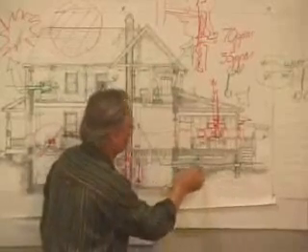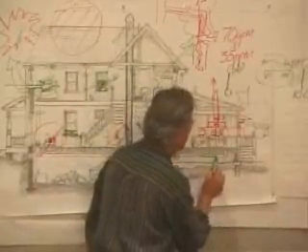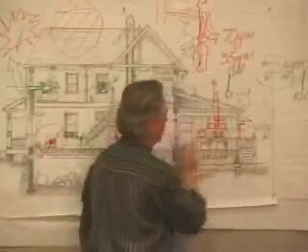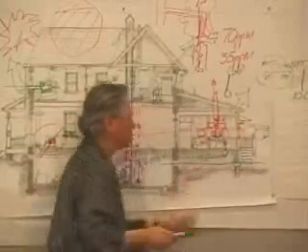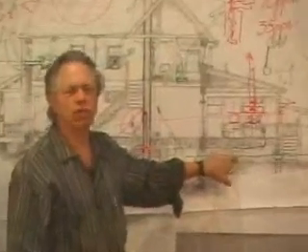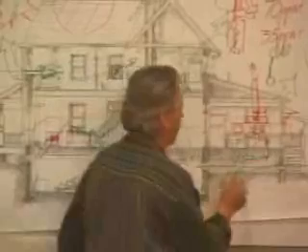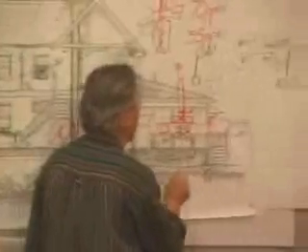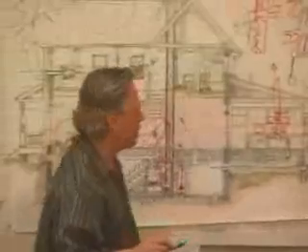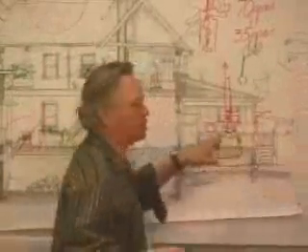Now, one of the things they have down here, this is a duct. It's running through that space, and it's blowing into here. And what happens if you got a hole in that duct at this point? You got a vacuum. What's going to happen? Where's it going to get air from? It's going to get air from the crawl space. There's a good chance that there's mice and rats and cockroaches and mold and dust and all kinds of things in this crawl space. If you have a hole in something that sucks, then it'll suck whatever's in that room into it, and this system is designed to distribute it through your whole house.